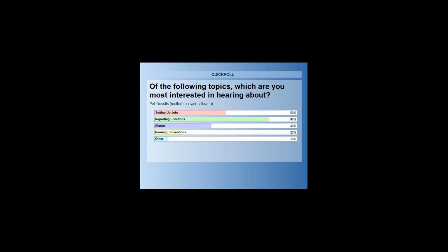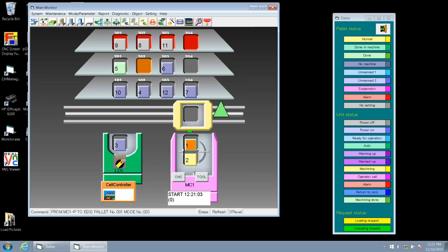All right, but now what we're going to do is set up a different job in the cell, which is actually our changeable fixture. So that's just a more efficient way of adding these jobs to the cell. You use a changeable fixture palette. This allows you to create and assign fixtures as needed. So we already have those programs in the cell, but we need to create fixtures to support them.